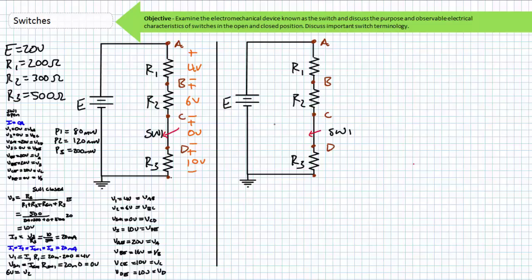With no current flowing through our circuit, no voltage drop will occur across any element. This being said, since there is a voltage rise, there will be a voltage drop somewhere within the circuit. The voltage drop appears across the open. Consider an open at node B, which necessitates the introduction of another node I'll call B'. No current flows through the circuit despite the fact that the switch is closed.